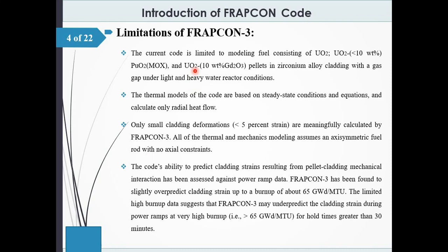has some limitations. First, the limitation is related to the pellets, and the current code is limited to modeling fuel consisting of UO2 and PuO2 for MOX fuels, and UO2 or UO2-Gd2O3 pellets in zirconium alloy cladding with a gas gap under light and heavy water reactor conditions.